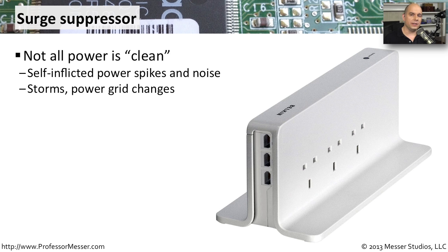You want to be sure that you have a surge suppressor that's able to take a lot of the spikes and the surges coming over those electrical systems and even them out so that your computer is not subject to those. If you have a heating or cooling system or other devices that are directly plugged into power, then you know that there can be surges that occur. These power surge suppressors are going to help a lot to clean and level out those surges that you might happen to get. If you do receive power spikes, these surge suppressors are very good at preventing those spikes from getting to your computer. They'll simply take that excess power and divert it directly to the electrical ground.